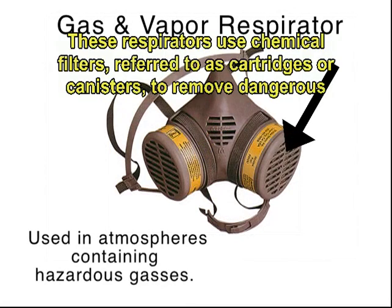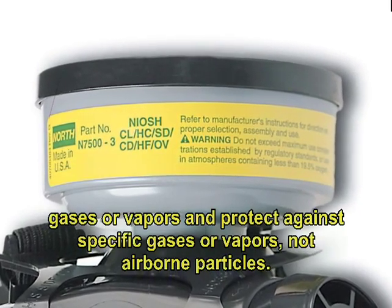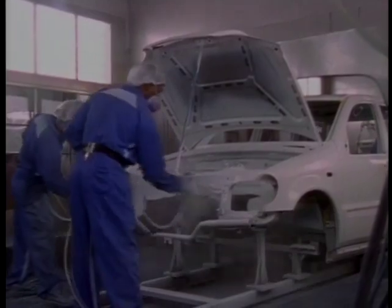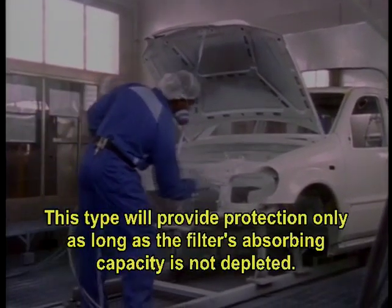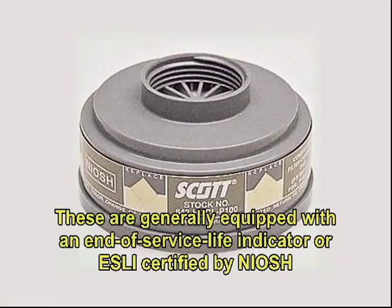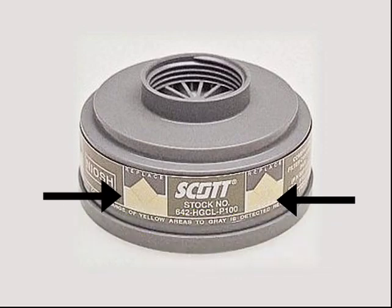These respirators use chemical filters, referred to as cartridges or canisters, to remove dangerous gases or vapors and protect against specific gases or vapors, not airborne particles. This type will provide protection only as long as the filter's absorbing capacity is not depleted. These are generally equipped with an end of service life indicator, or ESLI, certified by NIOSH to warn a user of the approaching end of adequate respiratory protection.